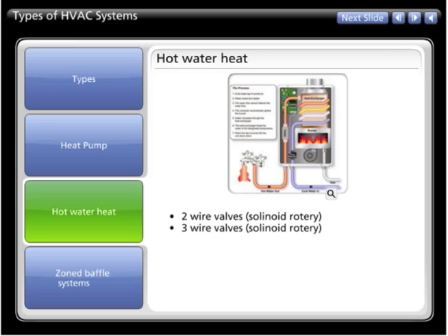The process of hot water heat. First, a hot water tap is turned on. Water enters the heater. The water flow sensor detects the water flow. The computer then automatically ignites the burner. Water circulates throughout the heat exchanger. The heat exchanger heats the water to the designated temperature. When the tap is turned off, the unit shuts down.